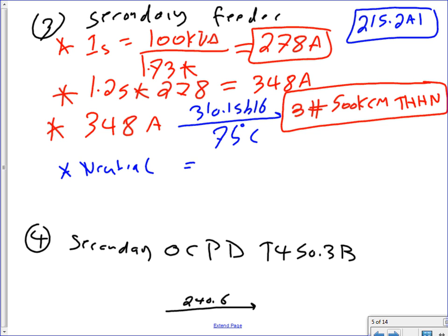What happened to the neutral, Chad? I'm going to derate the neutral. If you go higher than 200 amps, always apply the derating for the neutral. Always. Am I higher than 200 amps? Yep, derate the neutral. So here's my 3 conductors, the 3-phase ones. Why THHN? We're inside the building. Can I do the neutral now? Let's go to the neutral.